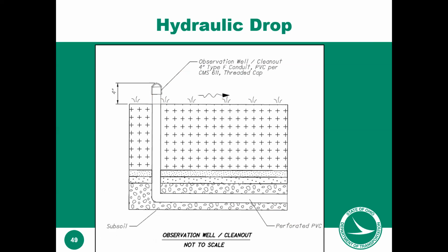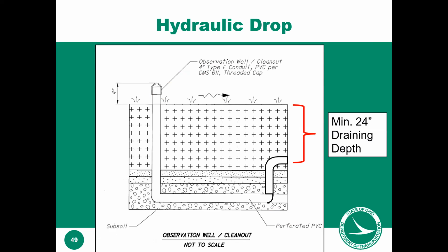Also, most bioretention cells are that deep, 40, 45 inches or whatever. You can elbow them up. I know that animation's kind of crude, but you can elbow them up to only 24 inches deep, which means if you have any kind of catch basin, it's already going to be down 30 inches plus, just where pipes are put due to freeze level. So if you can go up 24 inches, any place you have any kind of catch basin in the field, you can outlet a bioretention cell to it, which means they fit in a lot of places. There's some places up in Northwest Ohio where it's ditch to ditch to ditch, where it's all flat, where these might not work, but in a lot of places they do fit.